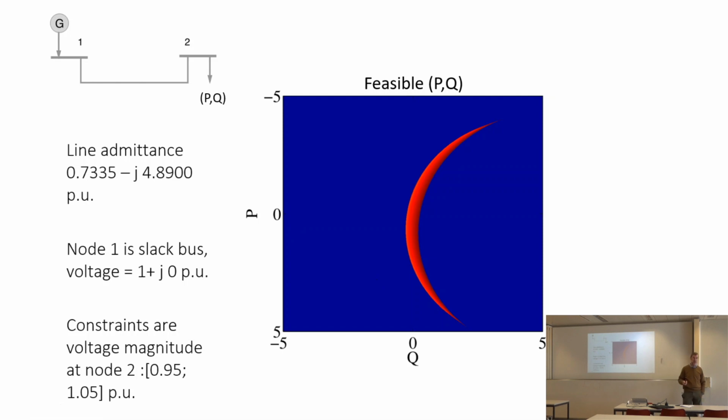So this is showing the problem of the AC optimal power flow. We are working on sets that have this shape. Of course, in reality, things are not as simple as this and not easy to visualize, because even in a single line, we will be three-phase typically, so it will be in dimension 6 and not 2, where I stop being able to do nice graphics. And there will be not just one node, of course, but a few thousands of nodes in any network, so we're in dimension several thousands. But it has been invariably found that we always have this problem. We have a non-convex problem here.